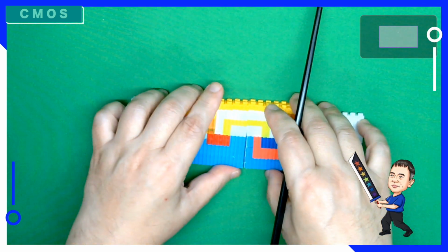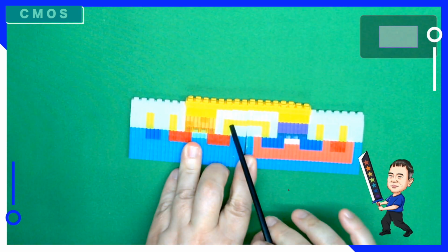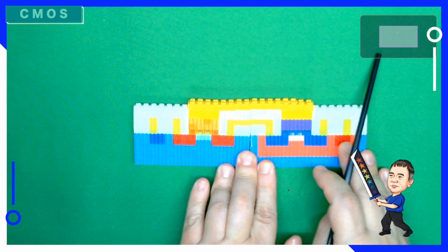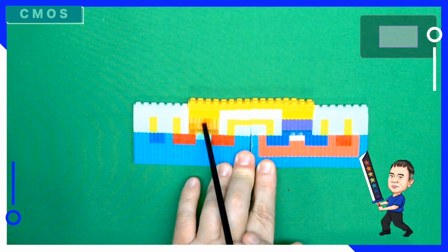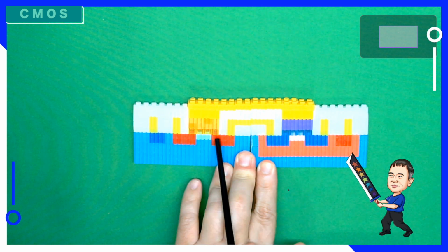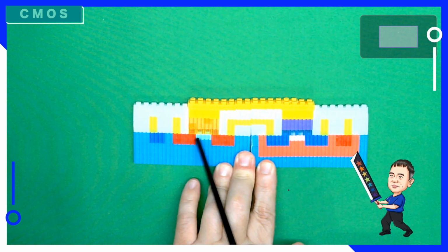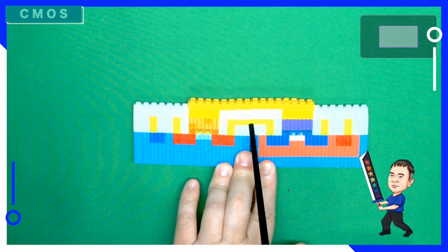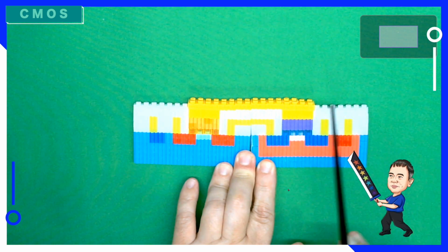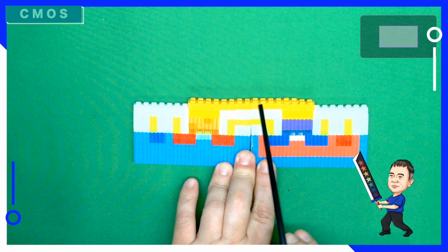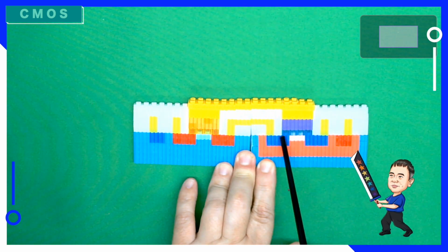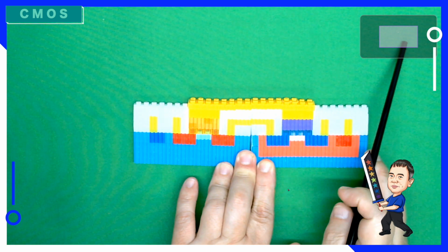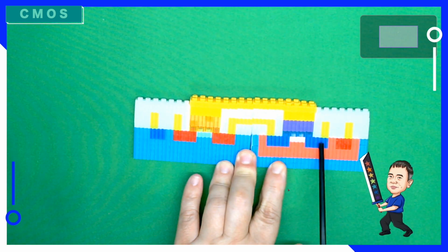And I can connect the output together. Gate together and output together. So when you apply a positive voltage, the signal will come here, and the N channel will open, so the signal will come here to the output. When you apply a negative voltage, the P channel, P stands for positive, electron hole channel, will open.